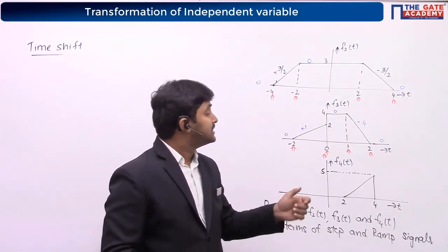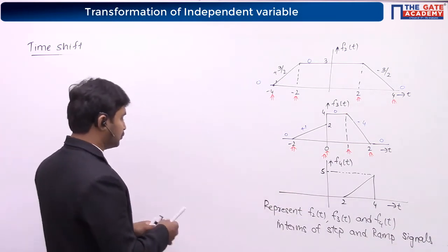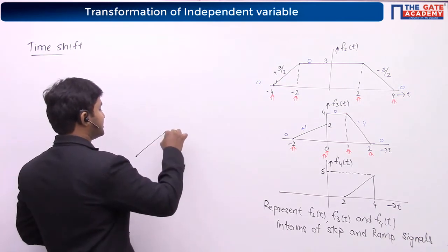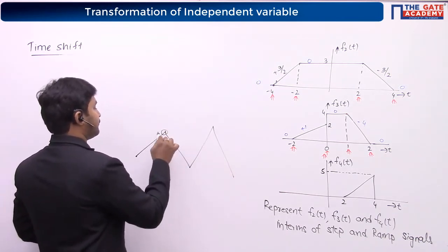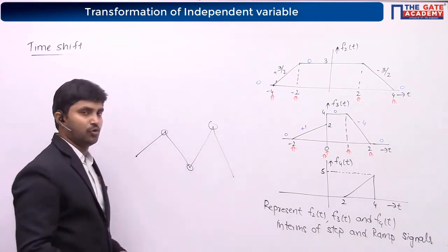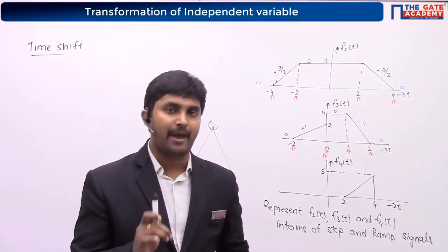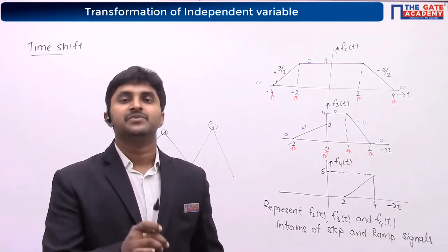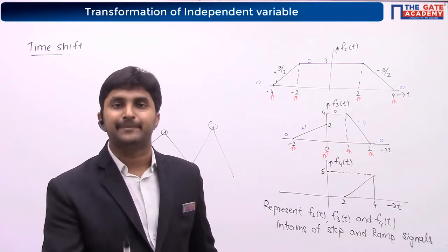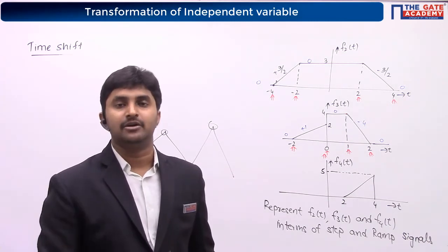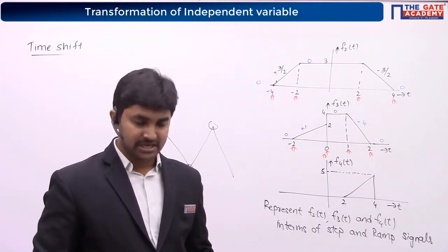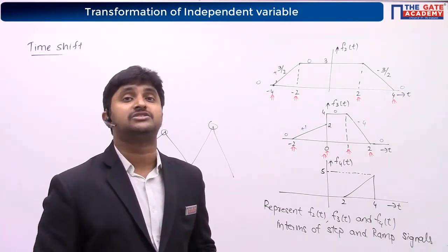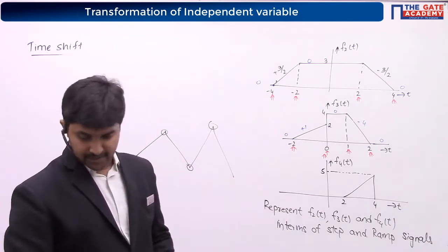And whenever there is a sudden change in the value of slopes, then we indicate it with the term ramp. And it is very much possible that both step and ramp can exist at a single point, and those are the points where many of us make mistakes, right?